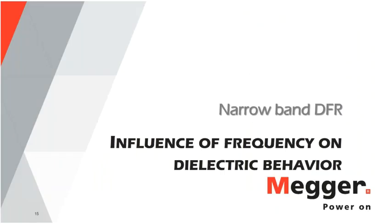Okay, so it turns out that narrowband DFR testing, where we examine the power factor as a function of the test voltage frequency, holds a key for improving a power factor test's potential for success. So let's turn and examine the influence that frequency has on insulation behavior.